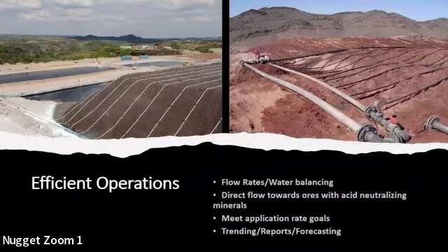It is a systematic modeling approach that uses measurements directly from the CPTU, so you can calculate directly the cyclic resistance ratio and the cyclic shear stress from the readings.